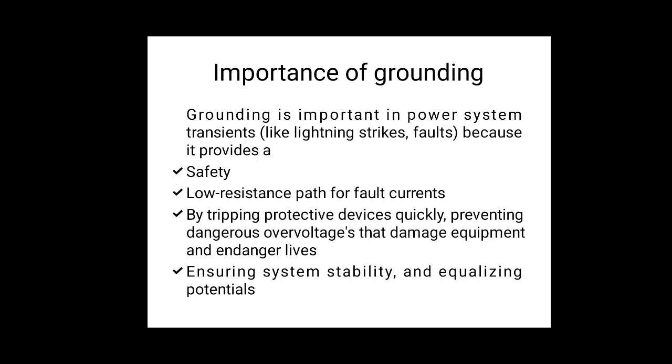Next, importance of grounding. Grounding is important in power system, which is used to provide safety, a low resistance path for the fault current, and by tripping protective devices quickly, it prevents over voltages and damages and ensures the system stability and equalizing the potential.